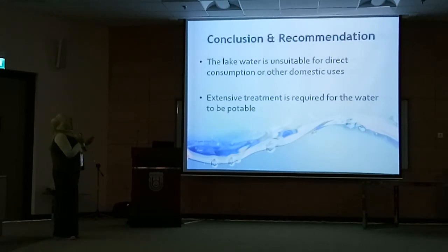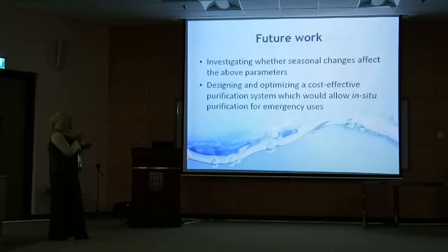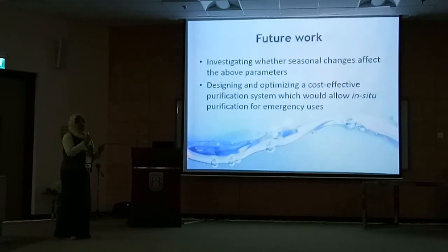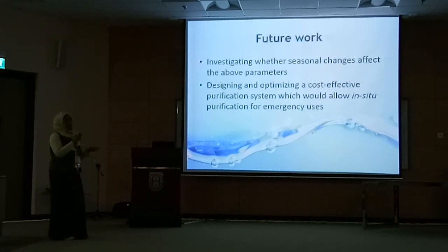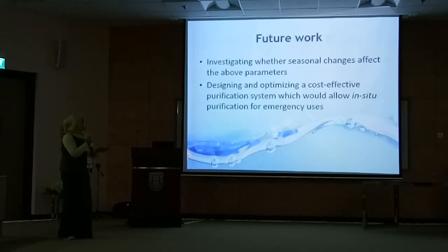So we are almost at the end now. The lake water is unsuitable for direct consumption or other domestic usage. Extensive treatment is required for this lake water, and for future work we need to check the effect of seasonal changes. Malaysia has rainfall almost 8 months of the year, so we need to check whether this rainfall affects COD and BOD and also dissolved oxygen. And also designing and optimizing a cost-effective purification system that would allow in situ purification for emergency usage.